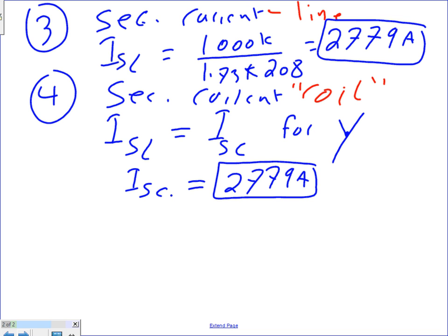What comes out of the Y is going to go through the line. What comes out of the delta, every time you have an intersection, it's going to be added to other currents. Delta Y is just a one-way street. It's the same current. The current comes out of here. Where is it going to go otherwise? If it's a delta, there's a fork. Okay. Up to this point, we're cool? It's straightforward.